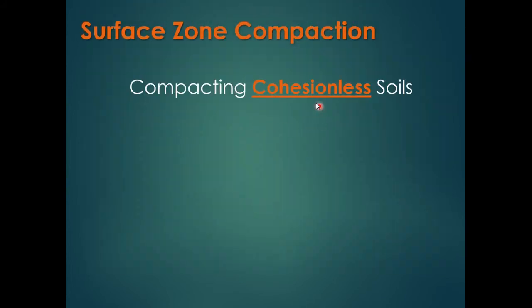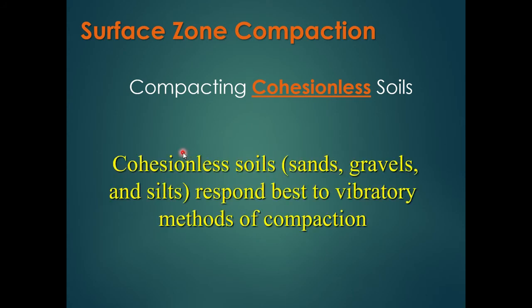All right, compacting cohesionless soils. Sands, gravels, and silt respond best to vibratory methods of compaction. Okay, keep in mind if we have a high water table, we're going to start liquefying the soil. So sometimes we have to turn off that vibration. Cohesionless, sand, gravels, and silts.